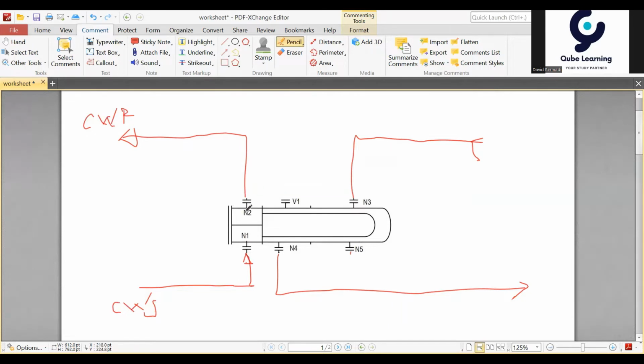We need to ensure that the tube is cleaned out by backflush. So I have to redraw it to ensure that the bypass is accommodated in this station. Basically, we're using a counter current exchanger because it works very well, since the heat transfer is better than the co-current design.